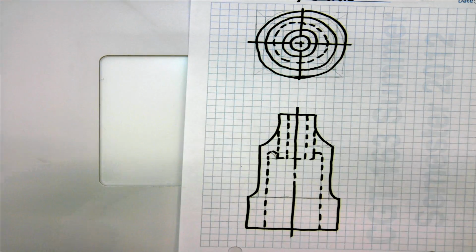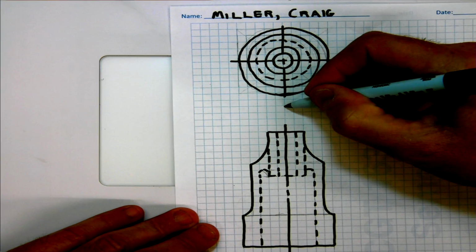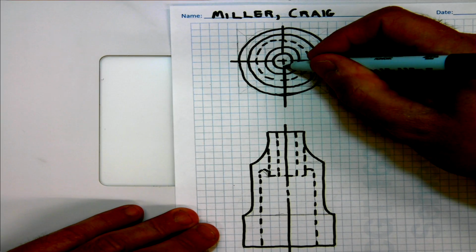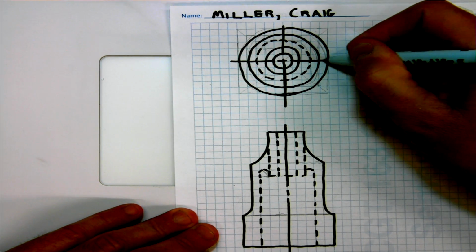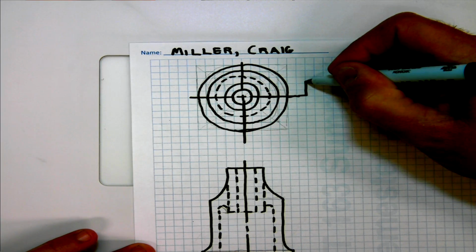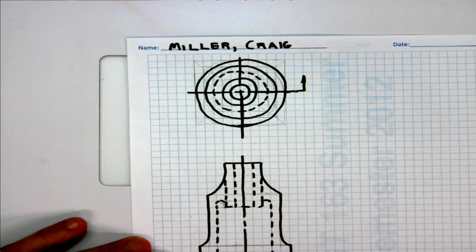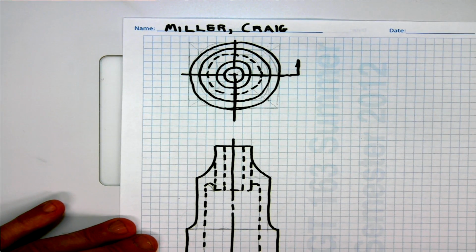So now we want to create this part as a half section. Remember, in a half section, a cutting plane starts here, and there's only an arrow on one end of it. So it starts over here, goes over here, and then goes up to right here. One arrow. If you did put another arrow, it would have to face in the same direction, but again, that is too much like work.